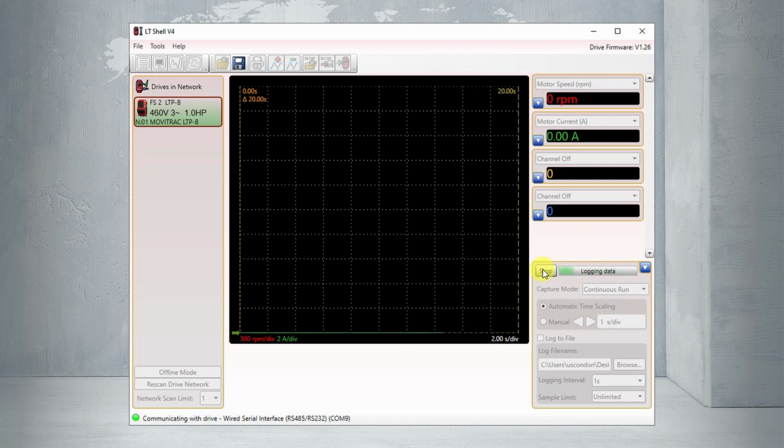What I'm going to do now is go to my VFD. I'm going to turn it on by enabling digital input 1, and I'm going to pick the preset speed. So what's going to happen when I enable it, it's going to accelerate from 0 to 1500 RPM. I'll let it run for a few seconds, then I'll bring it down again. We'll stop the trace and we'll take some measurements and see if those ramps are what they should be. All right, so that's what we're going to do. Digital input 5, by the way, because it is the fault sensor, has to be turned on so it doesn't trip. I'll be sure to do that. We'll go ahead now and collect some data.